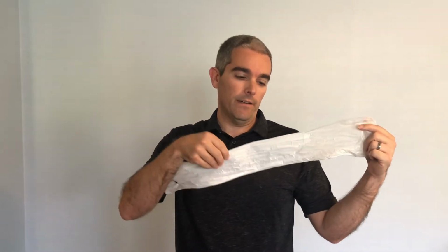Now, when we look at the limit state of yielding, the cross-sectional area has to be somewhere over here. This is the area that was resisting that pull, so it would be the end cross-section. So when we go to look at the yielding limit state and come up with formulas, that's what we're going to have to use.